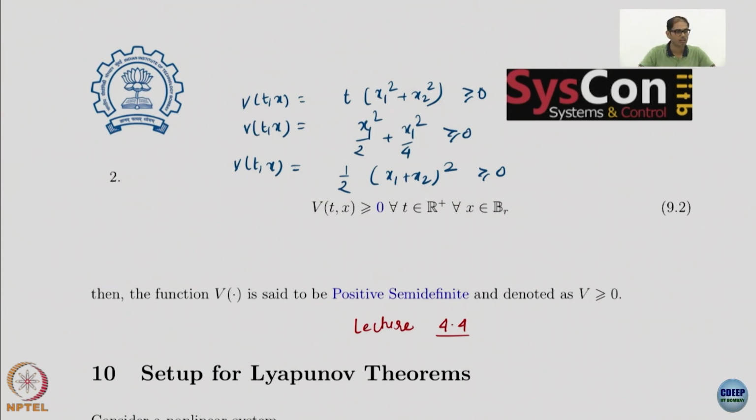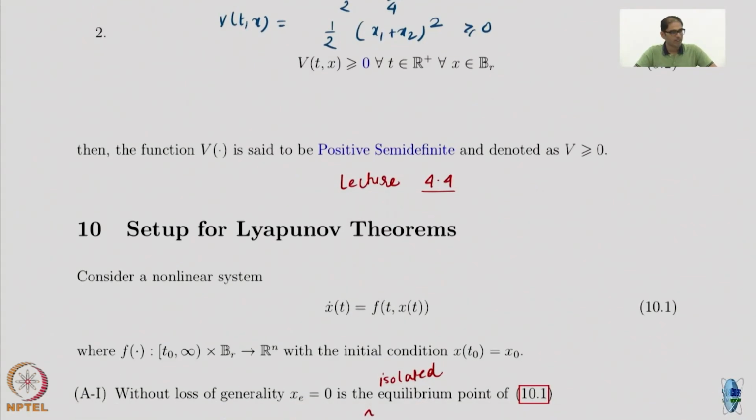Those are basically the LaSalle invariance principle and Barbalat's lemma and things like that. Those are methods that let you talk about global or asymptotic stability when V dot is only semi-definite, not V. V being semi-definite is still tough, though still not impossible; you can do some analysis there. Alright, any questions?